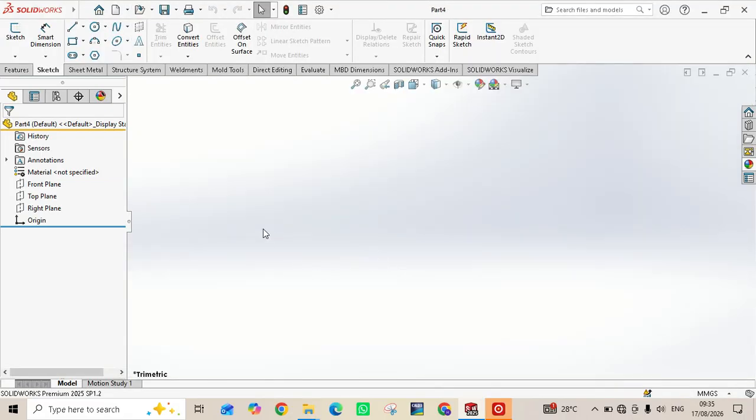In this video, I'm going to show you how you can create a sketch in SOLIDWORKS. So, firstly, before you start any sketch, you have to select a plane. So now, let's come here and select a plane. We have front plane, top plane, depending on which work you want to carry out. So now let's select a front plane.